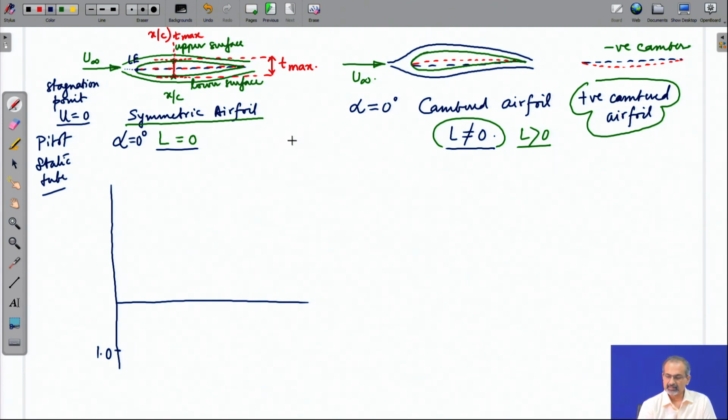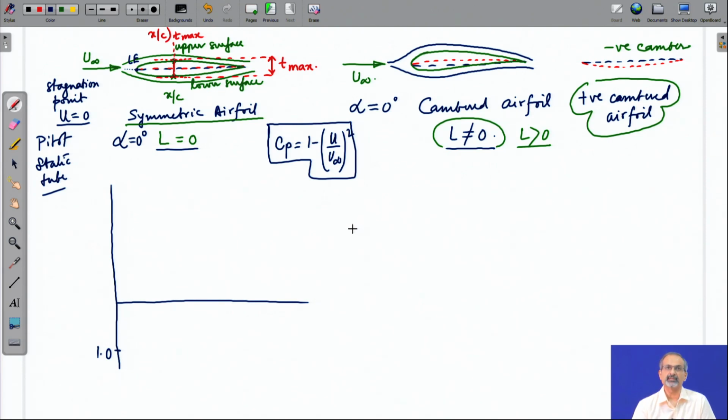Consequently, the pressure coefficient, if you consider it to be defined for incompressible flow, will be given by this expression which we studied earlier, and therefore, C p becomes equal to 1 whenever you have stagnation. So, if you are not considering viscous effects and additionally you are considering inviscid incompressible flow, then that is how it works: the peak value of C p will be 1. When we plot the C p distribution, we usually plot the positive values below and the negative values above.